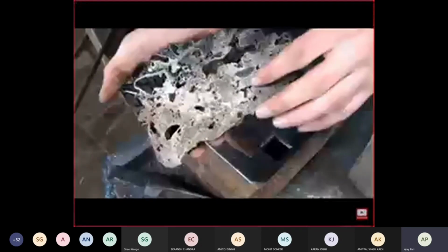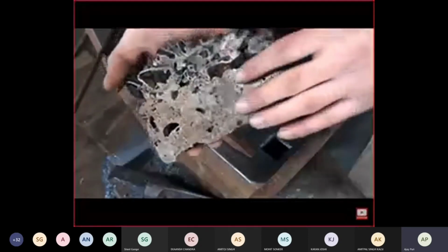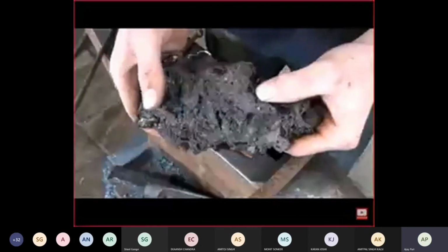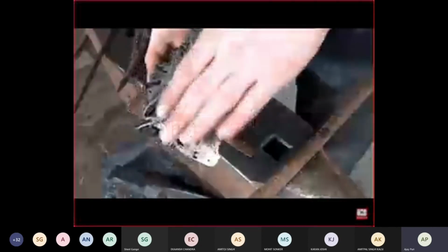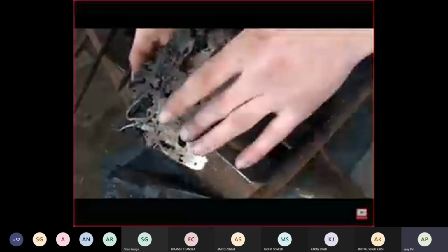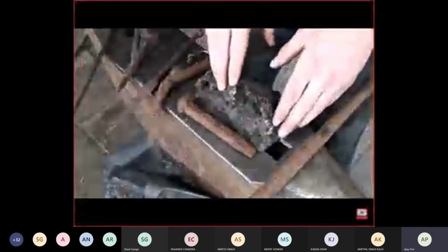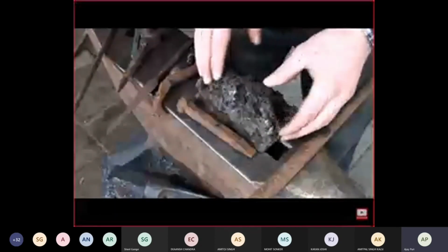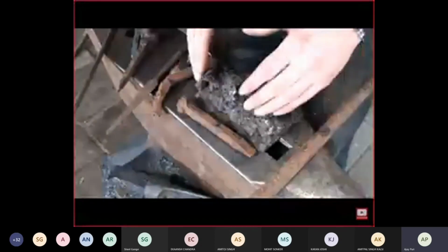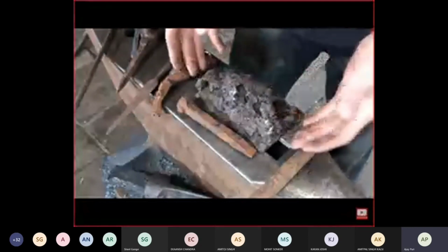Now, you shouldn't mistake this with cast iron, because cast iron is totally different. Cast iron means that the iron has actually been liquefied. In a bloomery furnace, this doesn't happen. It stays a solid and it clumps together. You heat it up and forge weld it back together in order to drive off whatever impurities are in there, in order to close those gaps that naturally form. This material, when it's produced, generally doesn't take up a lot of carbon, so it stays mostly iron, and the glass, silica type of stuff that lives alongside the iron is what you're left with.